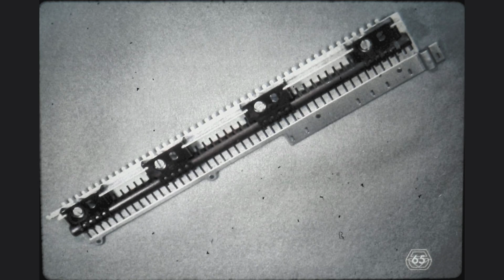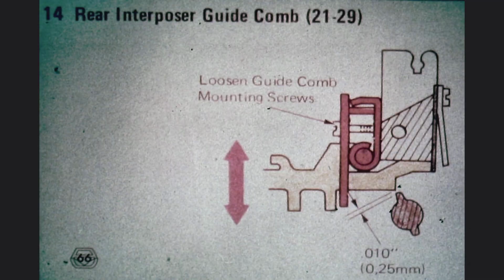It is important to mention that, when we wish to adjust the height of the compensator tube to establish the rest position of the character interposers, we should always loosen all of its support screws to the point at which it becomes possible to change the position of the assembly without much effort. Never try to tap the assembly for any reason, since it can easily be deformed and thus create a bind during the operation of the keyboard. The operator will then complain and call for your service, but when you get to the typewriter, the bind may never occur again, no matter how long you test. The same is true for cases in which dirt, such as eraser residue, has become lodged in the compensator tube.